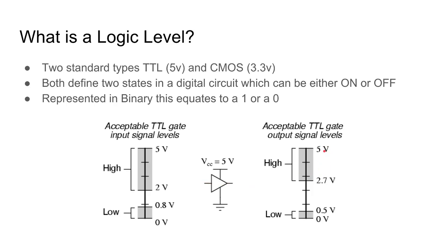So what the output level defines is it forces the voltage to be much more within the minimum input levels of other devices. So as more and more TTL devices are connected, they tend to self-correct if there's any sort of voltage variations in the circuit.